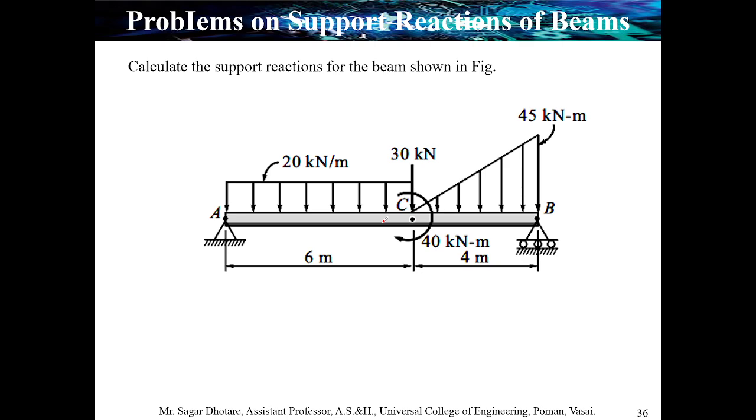While making the free body diagram, you will consider the basic support reactions, and you have to convert the uniformly distributed load and uniformly variable loads into single point forces. So use your pen and paper and try to make a free body diagram. You can pause the video also and just try to make the free body diagram.